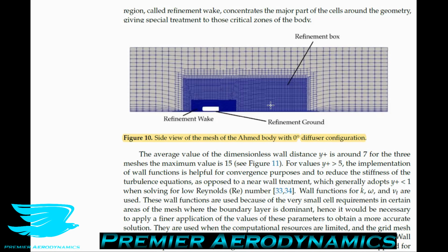Another thing of importance is that the refinement zones actually are not just in the wake regions, but also upstream a little bit. So why do we put them upstream a little bit? The reason is because there are not only downstream effects, but upstream effects. If, for example, you have an object and the flow separates behind it, that's going to have an upstream effect. There's going to be information propagating upstream that we want to make sure we capture properly. By having these refinement zones further ahead upstream, we can help ensure the accuracy of the solution is still high. If we were to keep the refinement zones just in the wake itself, a lot of that information would be lost and it would actually make the solution less accurate.